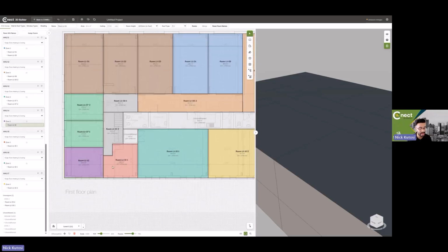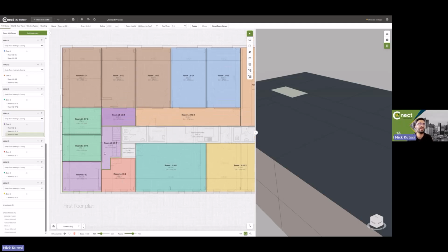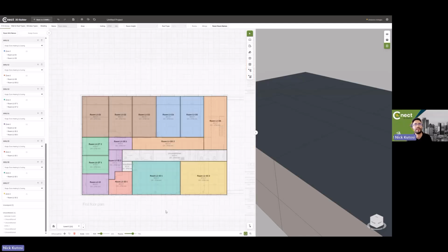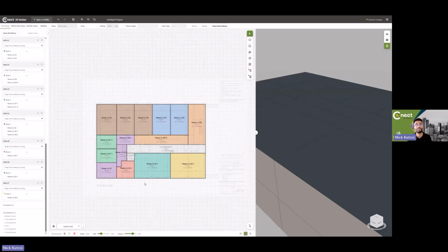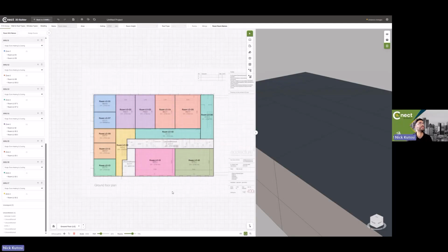you can click on that, click on the room. When you click on the room, it will select that zone. Then I can click A, and then I can click on the other rooms I want to assign to that same zone. So that's just a way of, I guess, copying over the zone to some unassigned rooms and reassigning that. So that's the AHU setup done. So a few different ways you can get there, as I've shown.